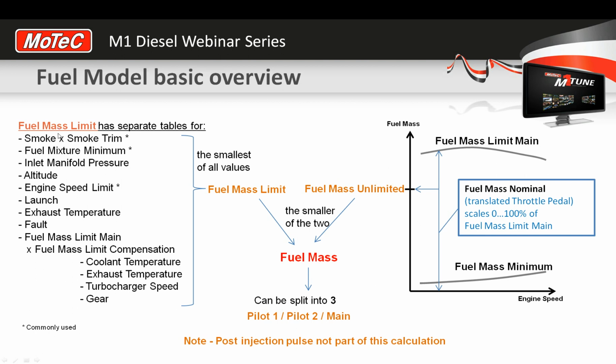It would drive like that provided all the tables on this left hand side had numbers higher than our example of 105. So if all of these numbers in all of these tables had, say, a milligram number of 300 in them, then the fuel system would just use the result of this very simple fuel calculation here.